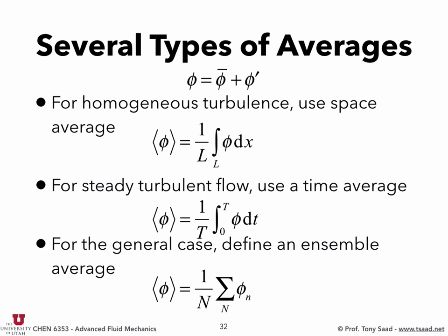Another one is the spatial average. So this is the time average as talked about. The other one is a spatial average, where you just average over a region in space or over the entire domain. The most useful average is the ensemble average. So say your average is an average over experiments, okay? We don't have to run those experiments. We just define the average that way and interpret it that way. The beauty of this definition is that it allows for time dependence to still be involved. You're not averaging over time, okay? You're averaging over experiments. And therefore, you can retain basic features of the time-dependent flow, okay? Average features of the time-dependent flow.